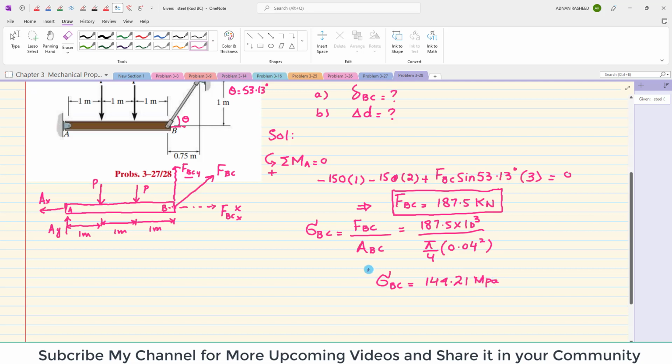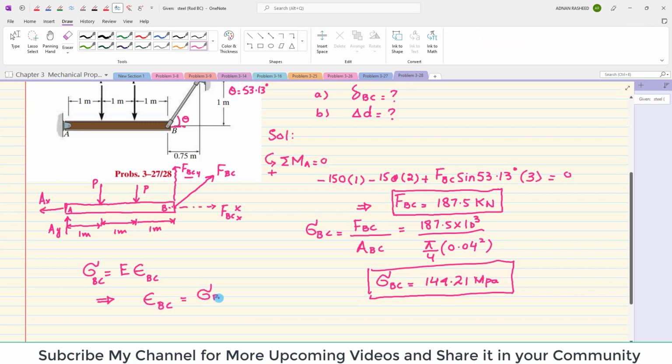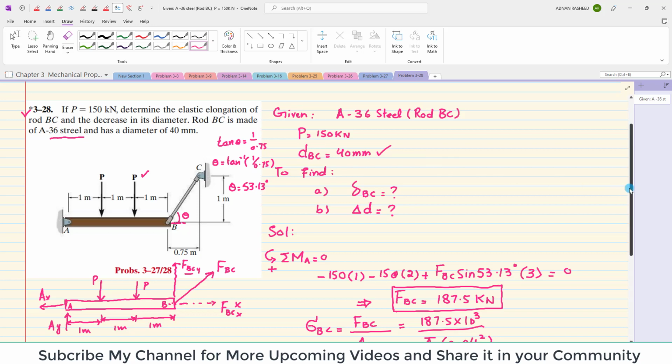Now I have this stress. I will go to find the strain. As we know, stress is equal to modulus of elasticity times strain. Clear? And this strain, strain in BC, epsilon BC, will be equal to stress BC divided by E of rod BC. Since it is A36 steel, you have to go to the table.